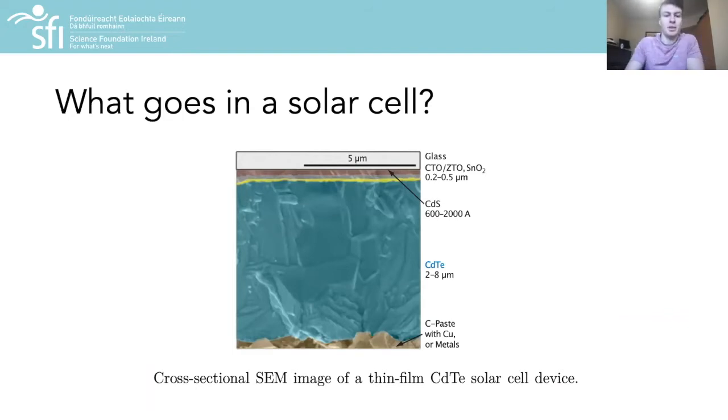In the middle, you've got an absorber material, which typically makes up the bulk of the solar cell and, you guessed it, absorbs sunlight and converts it to mobile electric charge or electric current. Usually this is interfaced with another semiconductor, in this case a thin layer of cadmium sulfide, which may or may not be made of the same material, to form a PN junction, which aids in the charge separation and thus generation of an electric current.